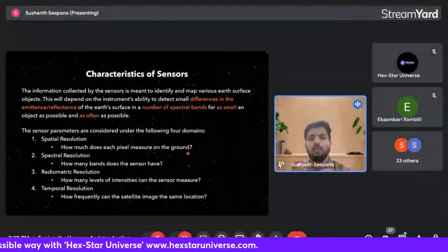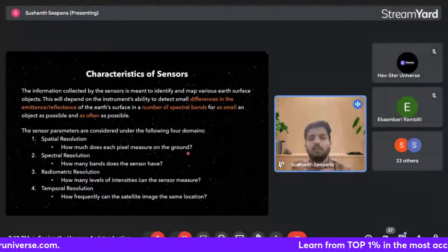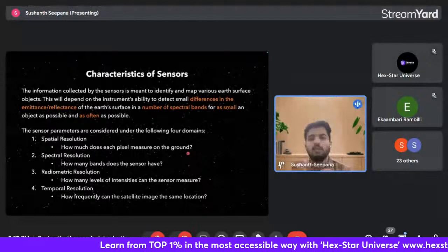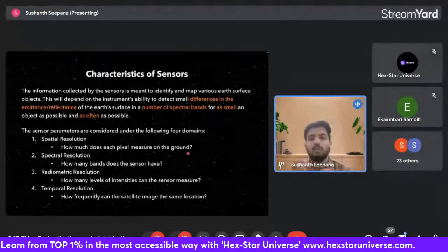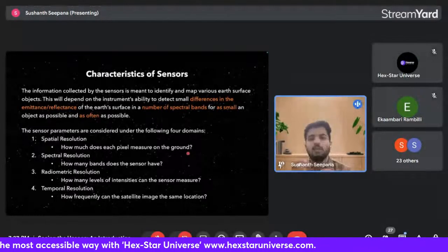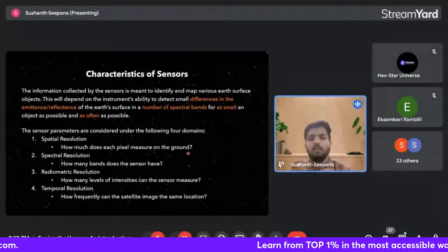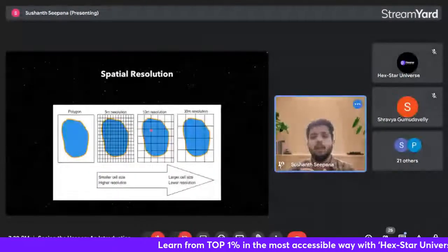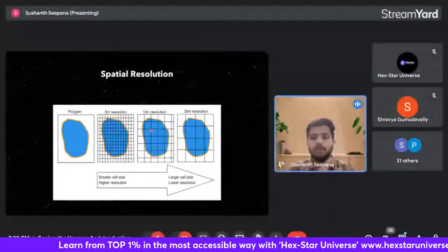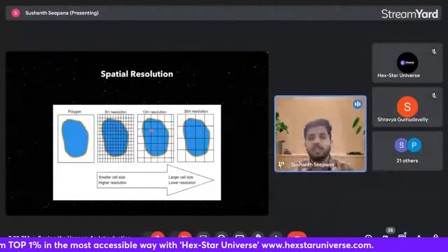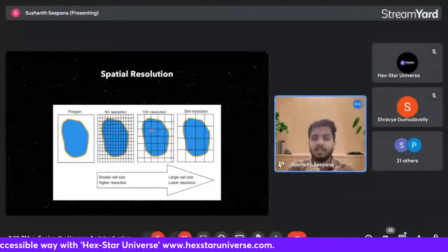So the fineness, let's say inside this there is a small chip which you can detect, which is a chip of 5-meter size. You can detect with 5-meter resolution data, but with 10-meter resolution data, you can't detect a chip that is less than 10 meters. So the resolution number 5 meter or 10 meter or 30 meter means that any object smaller than this value can't be detected. The initial Google Earth imagery, when you're able to see almost very clearly, is sub-meter, 30 centimeters. If you put a scale or something it cannot be visible, but anything bigger than a scale, you can see it very clearly.